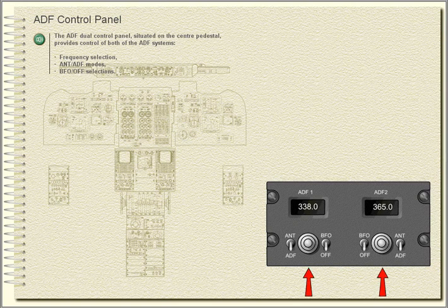ADF Control Panel. The ADF Dual Control Panel, situated on the center pedestal, provides control of both of the ADF systems' frequency selection, ANT-ADF modes, BFO off selections.